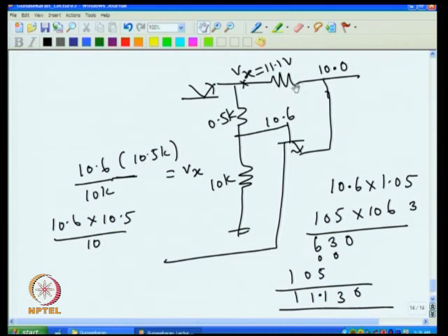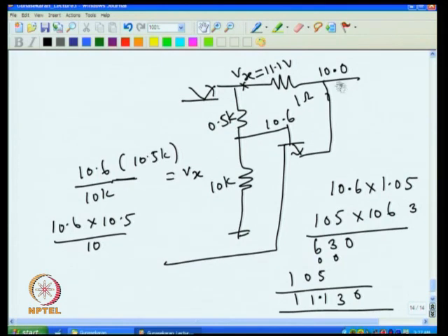That means if I had taken 1 ohm resistance, in our example we had taken 1 ohm and then current limiting short circuit condition took place at 0.7 ampere. Now if I take the same 1 ohm here, then to get 1.1 volt difference, because this is 10 and this is 11.1, to get the difference of V difference of 1.1 volt, I need current of 1.1 amps.